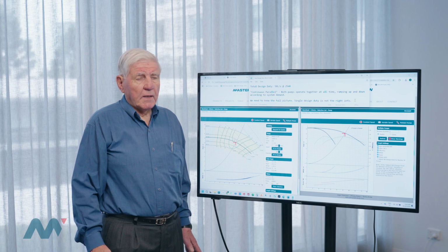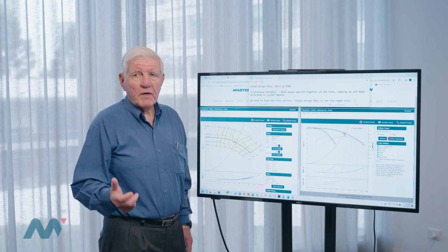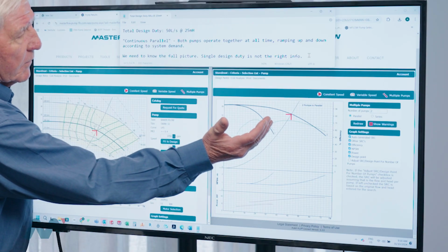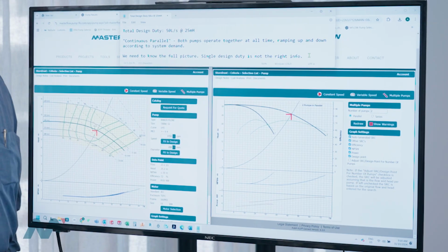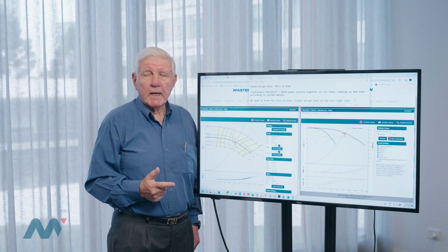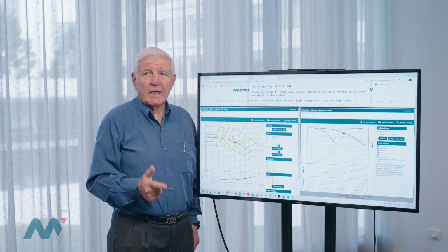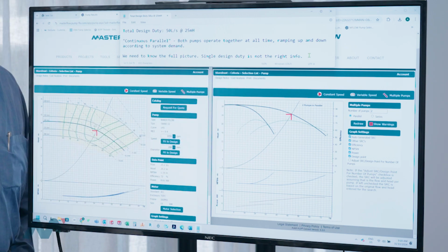Yeah, and that's understandable. If you throttle the valve in the two pump system, what you will do effectively is to bring this curve up to a situation where the pump curve does intersect that manipulated system curve. And then you will get an operating point where it could be satisfactory. But you cannot get it with a fully open valve with this system resistance curve. Just not possible.